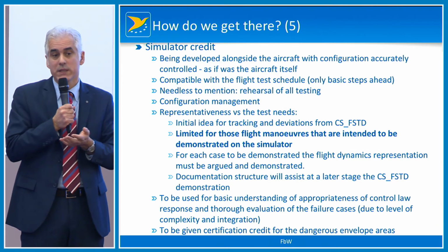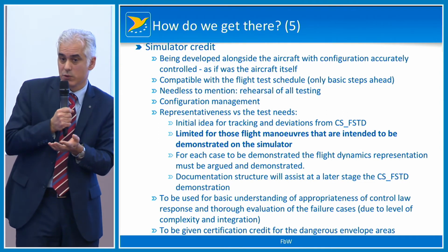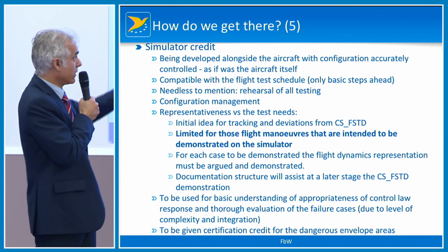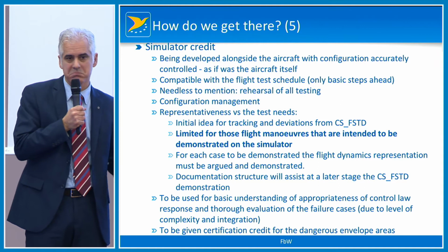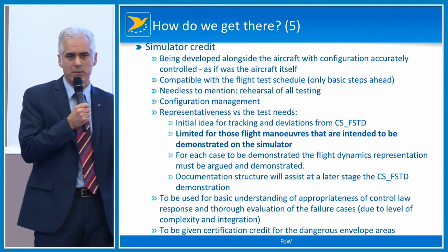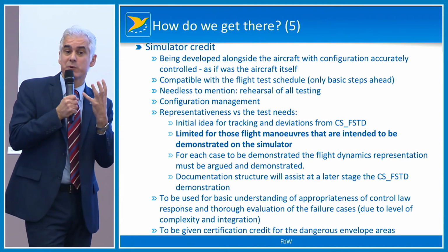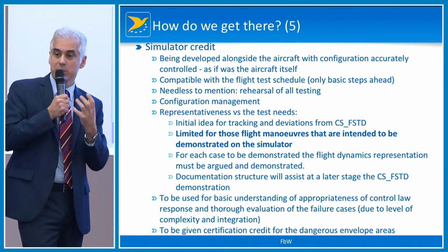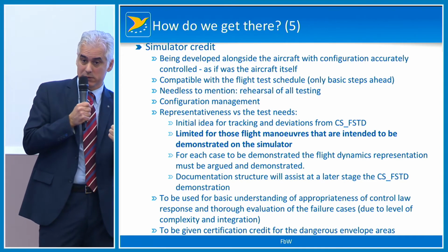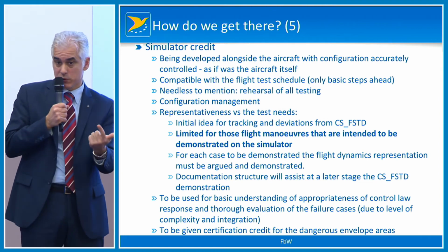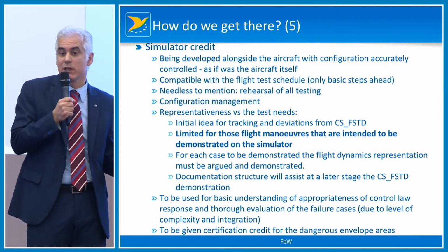Actually, we don't need to think too much about it, because our colleagues from Flight Standards already have a solution for training. If you go and look at the CS-FSTD, you will see a very long list of requirements: how much torque, how much velocities, how much you are allowed to deviate, in order to be good for training. If you're good for training, it means you're good enough, it's controllable, it's not dangerous to fly, so we don't have any negative training, and we certify simulators for those things.